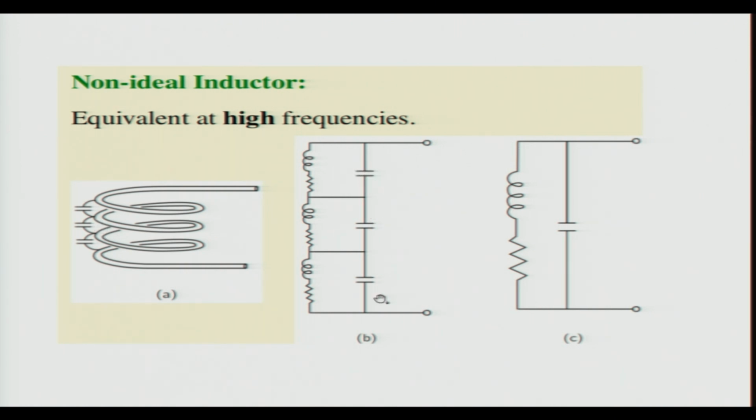This is not obvious, but again this capacitor, being distributed all along the wire, can again be approximated by a single lumped capacitor. So, this approximation shown here is again valid in the low frequency range. You can make what is known as a lumped approximation of a distributed element, provided your frequencies are low and the size of the elements is not very large. So, you can model this by lumped capacitors and inductors. This is of course a model, and it has its region of validity.